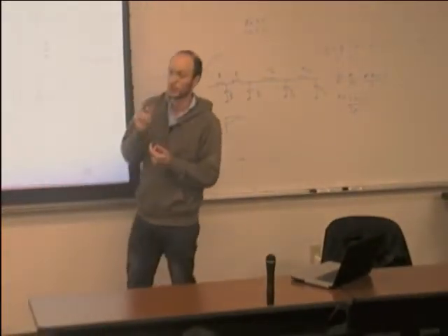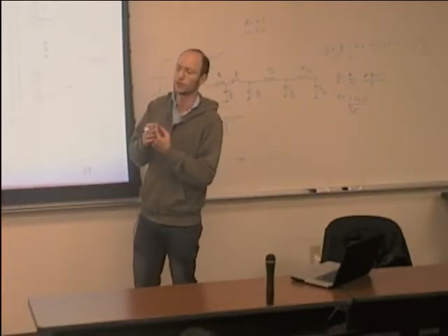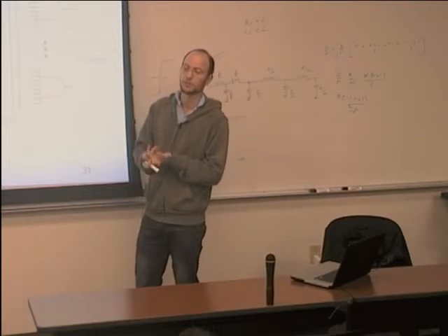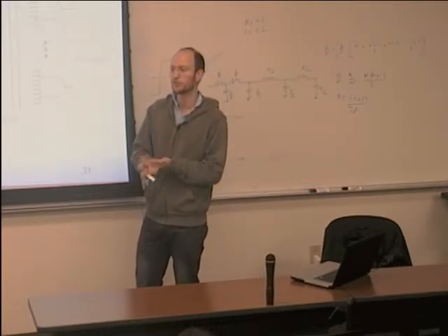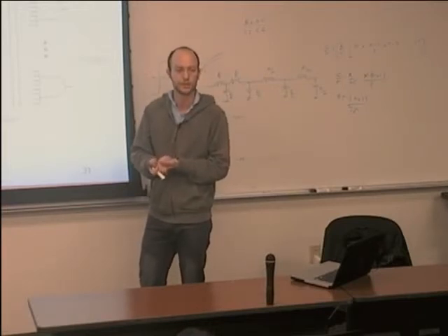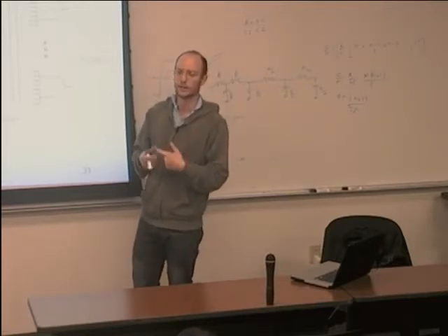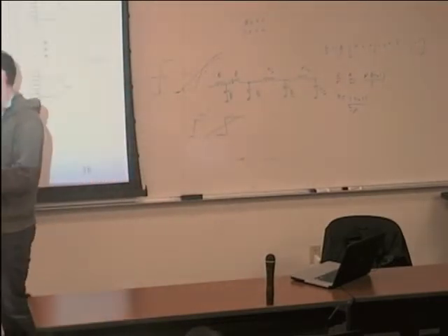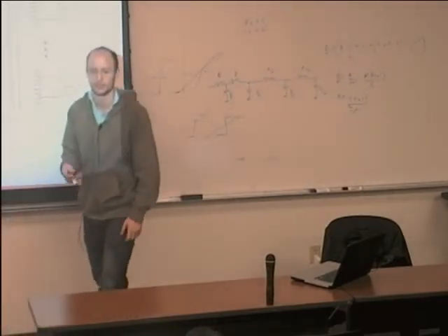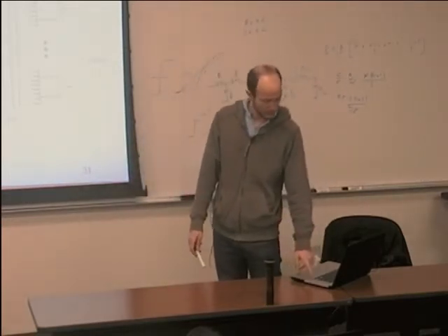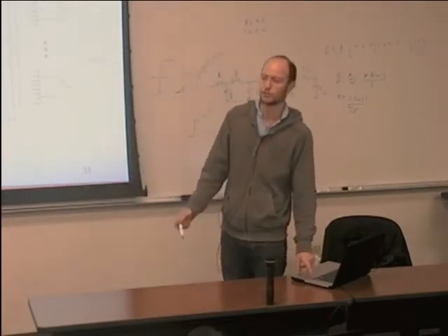There are 2 things. One is the path effort, so you need to calculate the path effort. Once we know the path effort, the optimal number of stages is essentially log of the path effort, and the optimal effort per stage is just about e, meaning the Napier number. So what represents the path effort for this decoder?